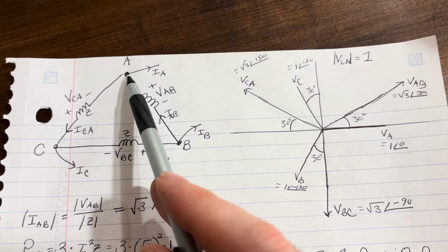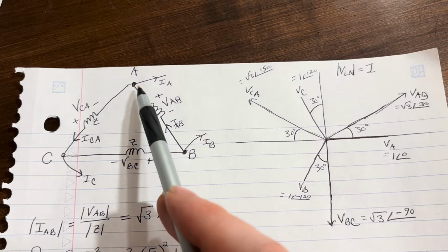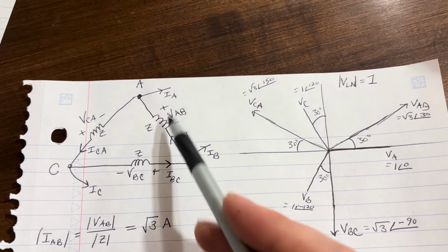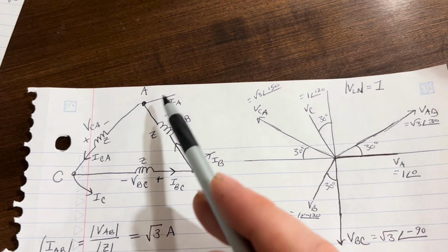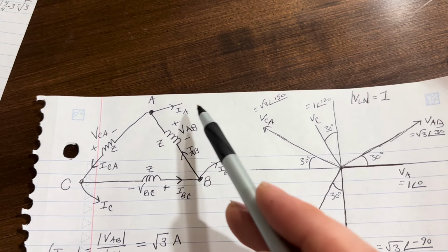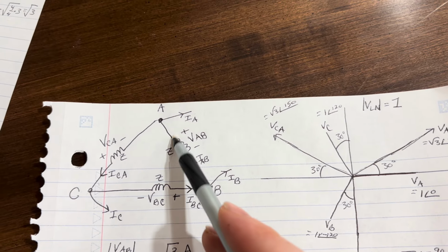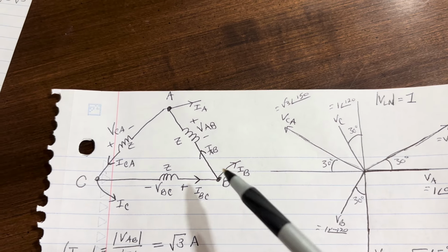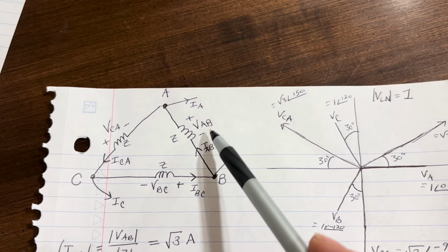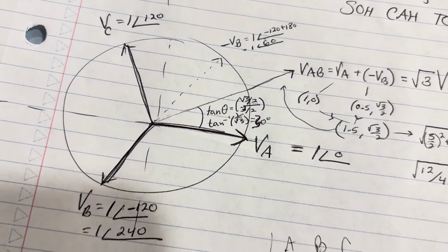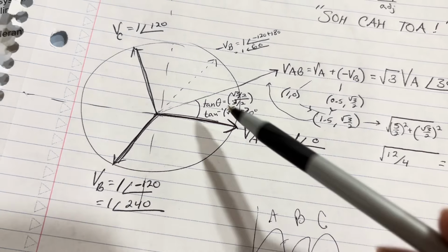If we have our delta source drawn this way, A, B, C, sources always have the current flowing from minus to positive for your voltages. Loads, you would define the current flowing in. It will help you out. Okay. We have VAB, VBC, VCA. Those are our positive sequence voltages. I'll get to how it's different from this because VA instead of VAB, etc.